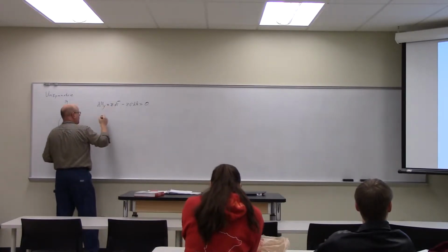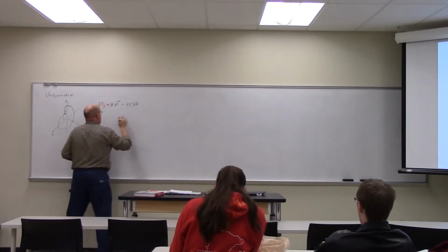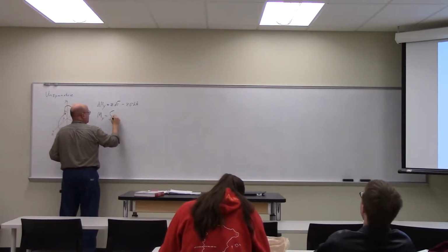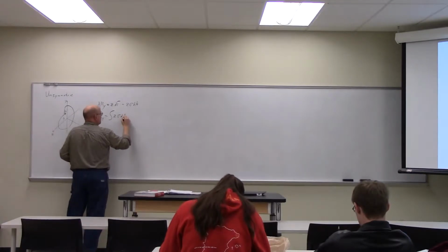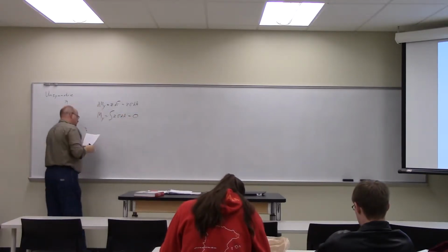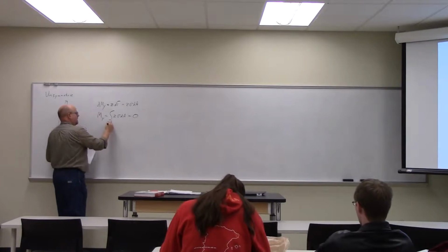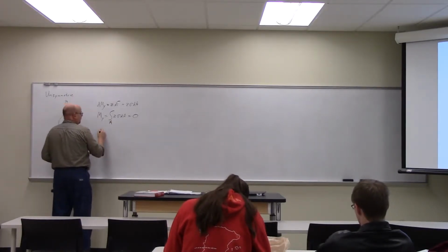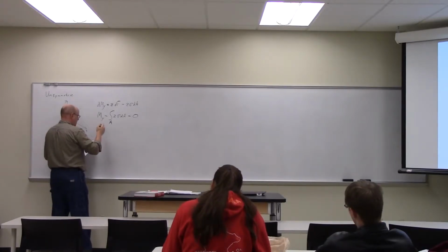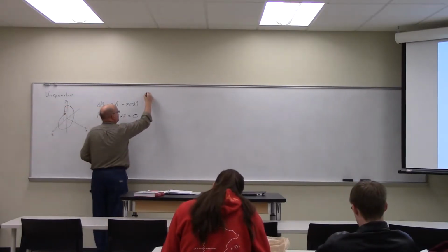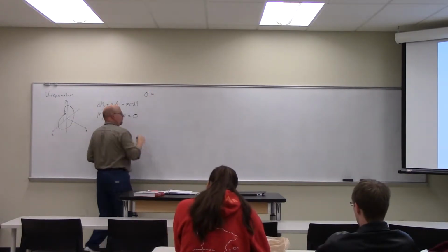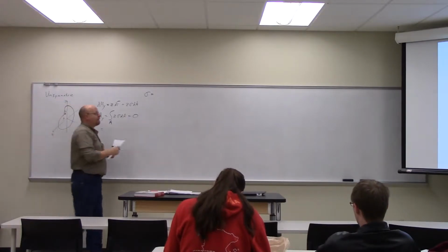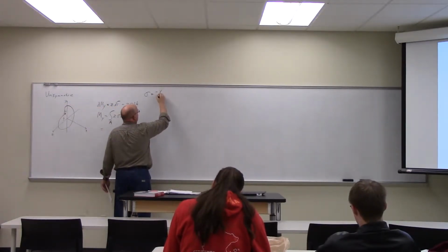Actually, the integration of those has to equal 0. Therefore, the integral of z sigma dA over the area has to equal 0. So do the substitutions that we did last time, same idea from our earlier analysis. Sigma was equal to what? Anybody remember? C over rho.